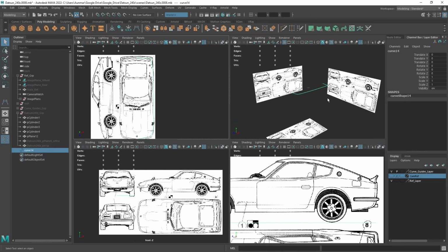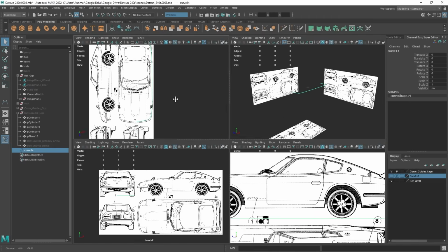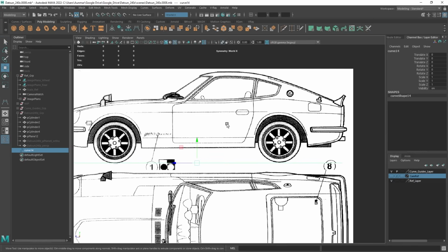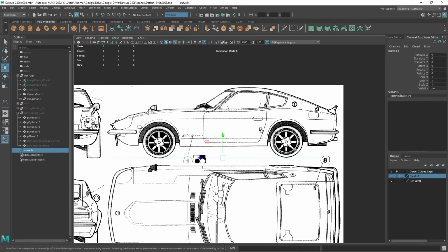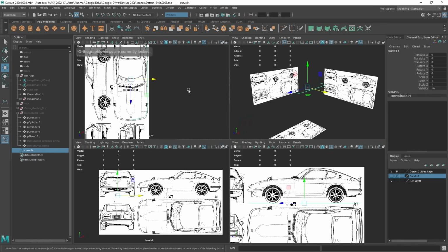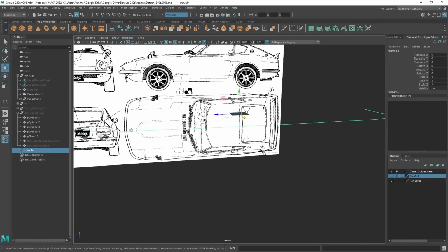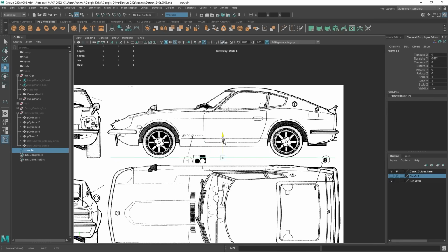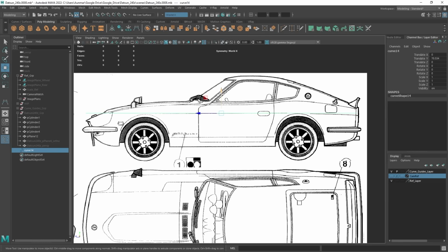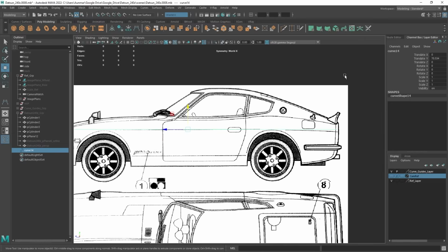All right, so now if we take a look at this in the side view, we've created this from the top. Now we need to make sure that it looks fine from the side view and our other orthographic views. I'll drag this. You can see that if you create curves from the orthographic views, it simply puts this right here on the grid plane at 0, 0. So now I just want to move this up, and then make sure these curves follow from the side view. You want to make sure that it at least matches in 2 orthographic views.